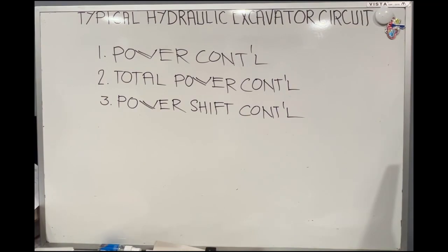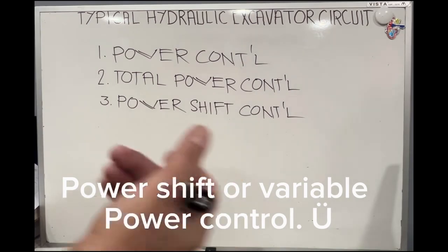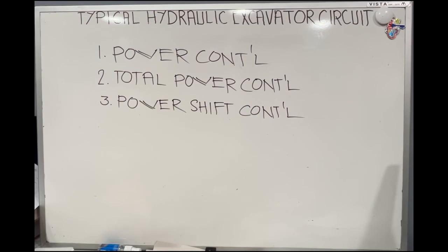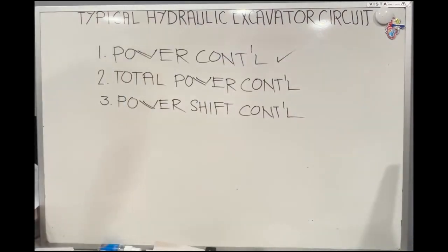And then the power shift control is from a control proportional solenoid or pressure reducing valve. The pressure is either proportional or inversely proportional to your milliamps. So I will also discuss that, but today I will only discuss the power control, which is the normal one.